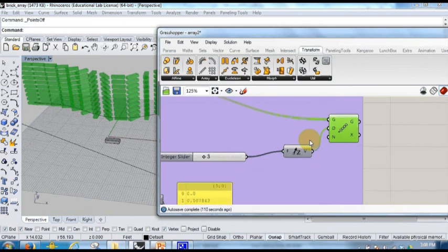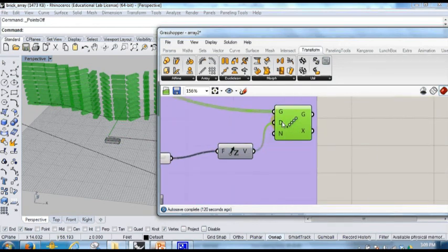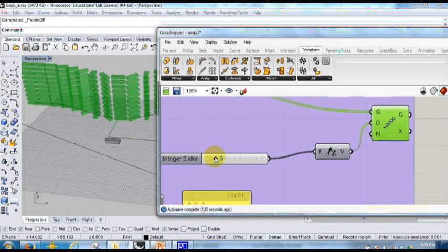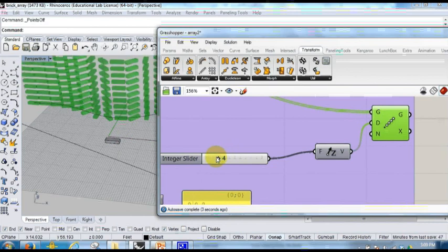The layer is actually controlled, like I showed you, simply by an array along the z-axis. So this is actually a component that allows you to duplicate the result along some direction. So in this case, the direction is z, right? And you have this control, distance, how far you want to move the duplication.